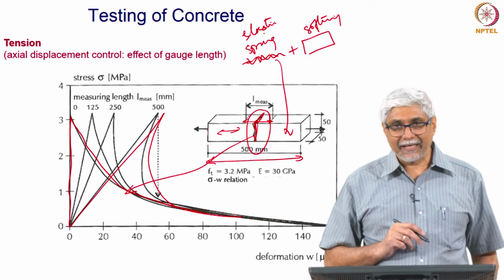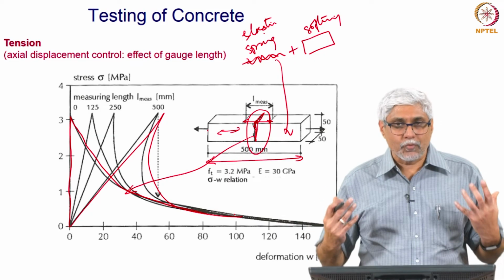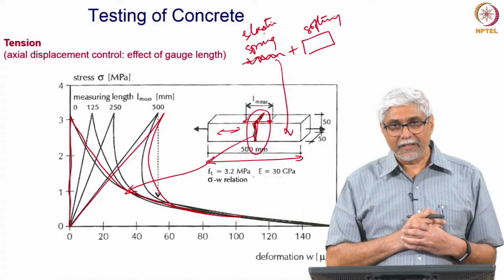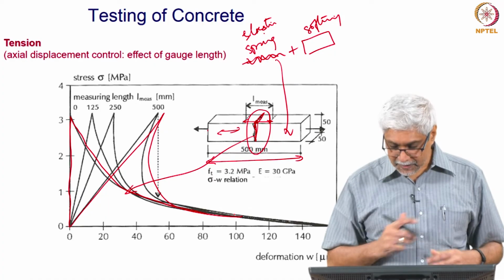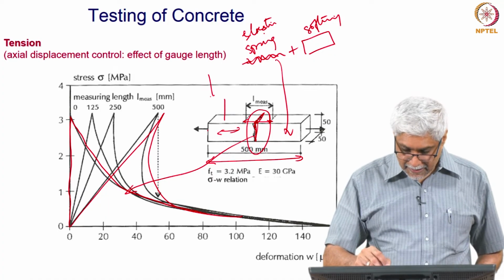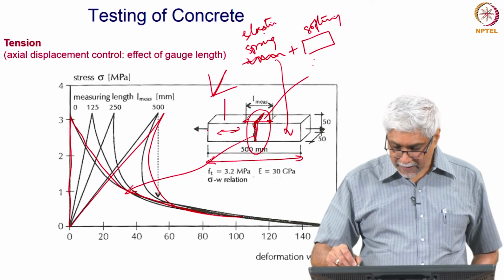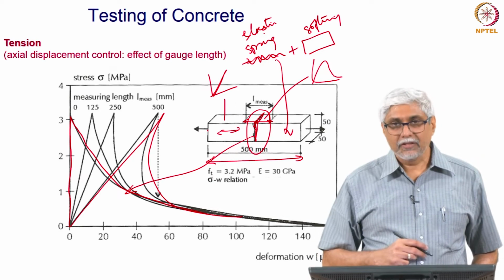So, I get snapback. What does a lot of snapback mean? Snapback means that energy is coming back from the elastic part when we are unloading. Okay. So, this part in your load displacement is doing this, and this part is doing the softening.